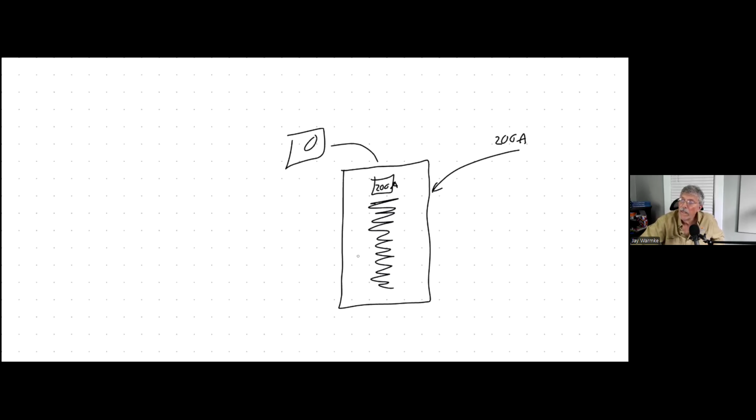So you might think that this thing is maxed out, that you couldn't use it to connect your inverter to, because you're going to be bringing more power in from your solar array. But the National Electrical Code says we can go to 120% of the bus bar rating. In this case, we could bring in another 40 amps because 120% would be 240.